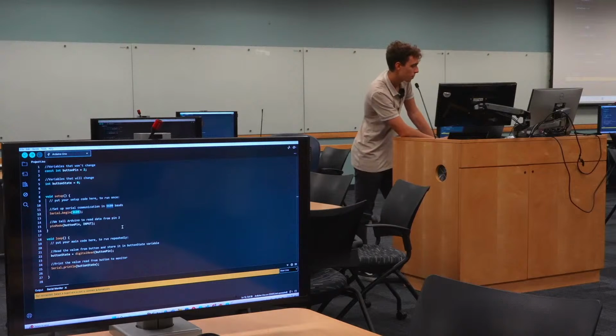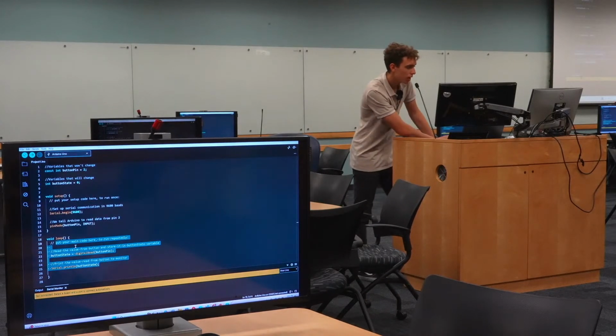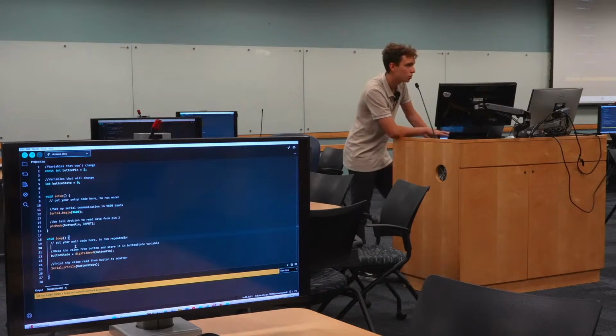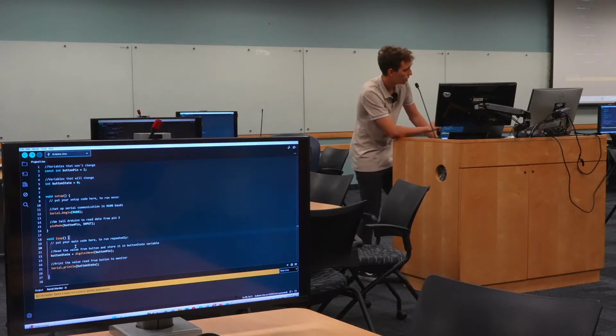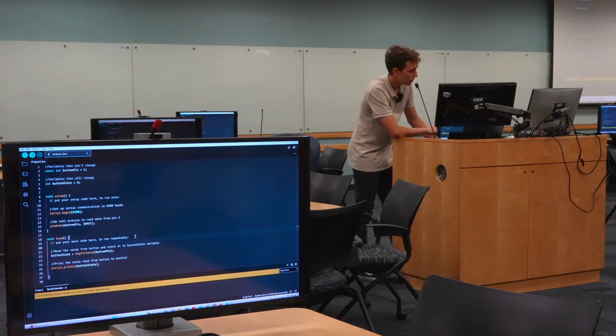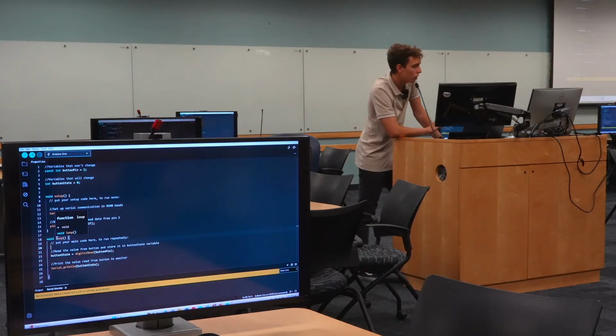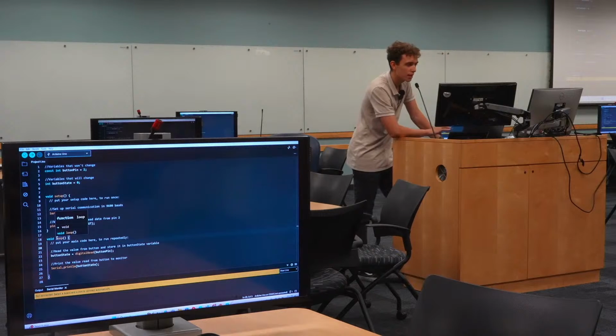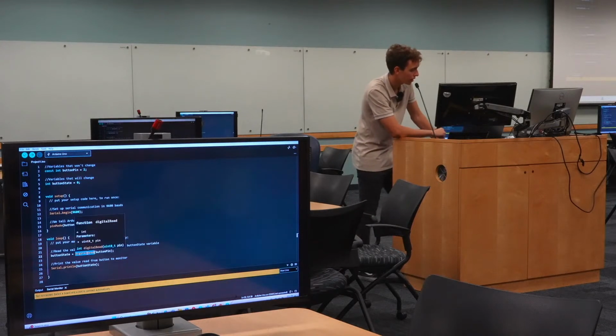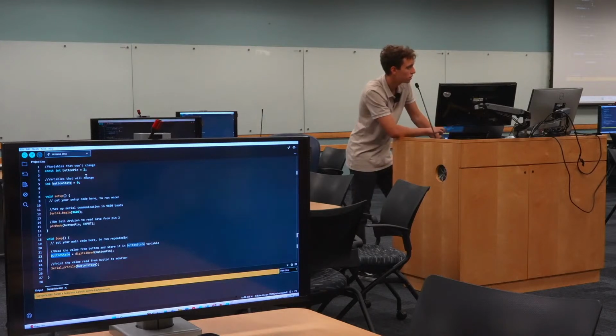And the third part and the most important thing is the logic of a robot, which, remember, is always in the void loop. And here you're doing all the business logic. Everything that you want the robot to perform, you write it here. Remember, that's why it's called a void loop. It's always running. It's endless, and you cannot stop it, basically, unless there's a coding mistake. So here, you're using the variable that we defined on top of it. Remember, it's always best practice to define the variables on top.